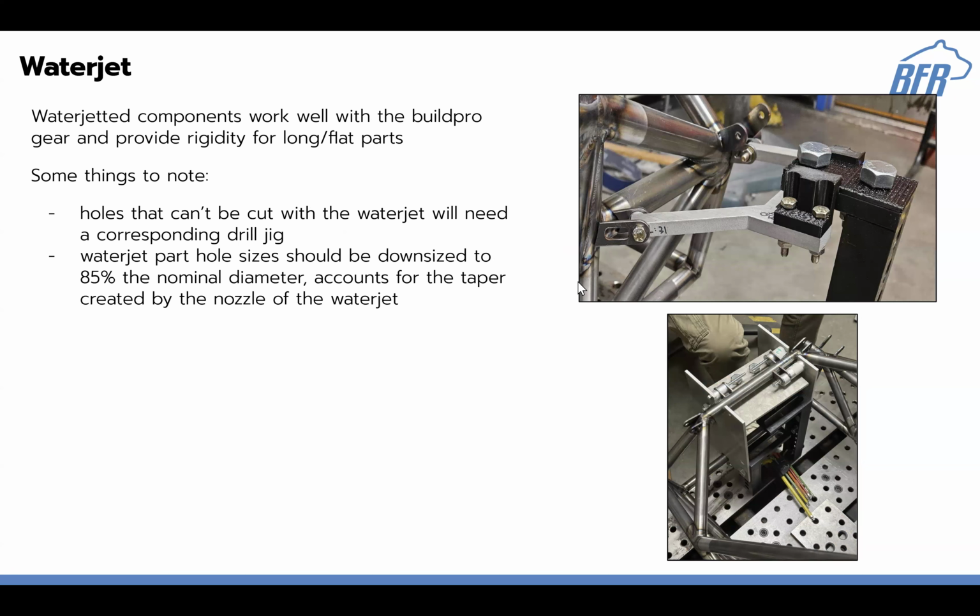And then one of the first materials you'll be able to use is aluminum or any sheet metal. We'll generally use a water jet to obtain these parts. Water jetting, if you don't know, basically shoots a high velocity stream of water with little abrasive materials inside. Oftentimes it's garnet or some sort of sand in there, some sort of abrasive that'll actually cut through any material. So this is really good for getting 2D profiles cut out of metal really quickly, really easily.